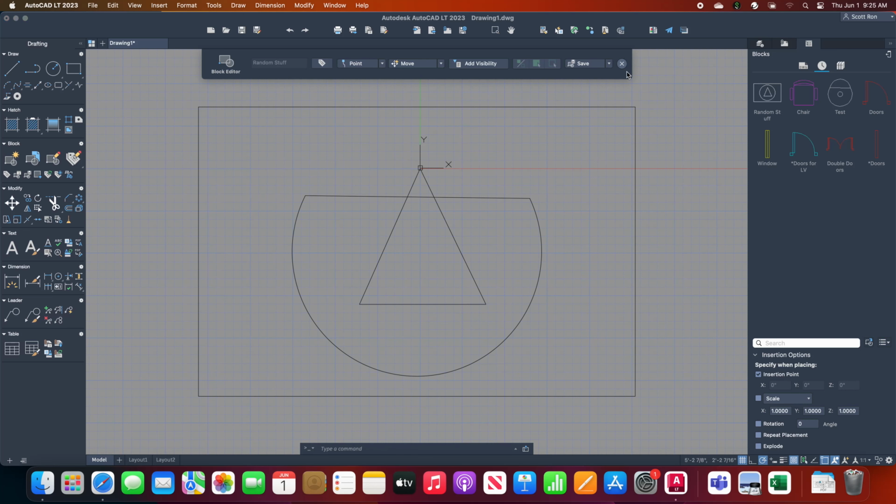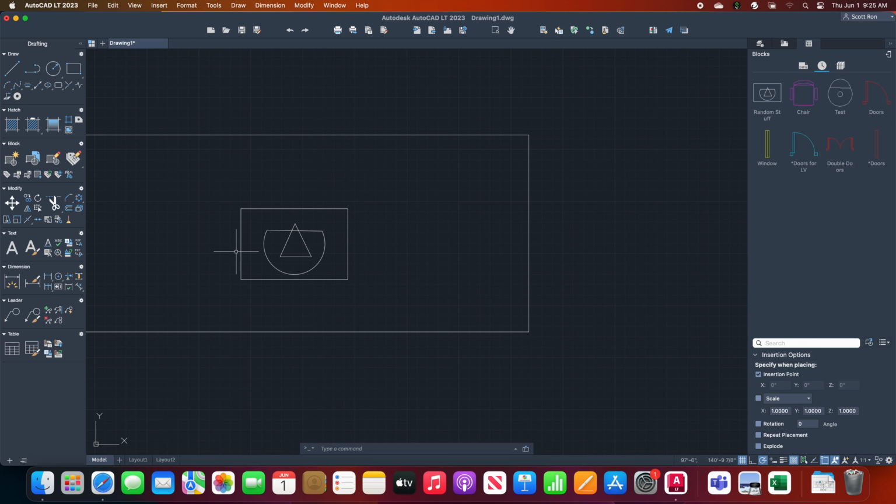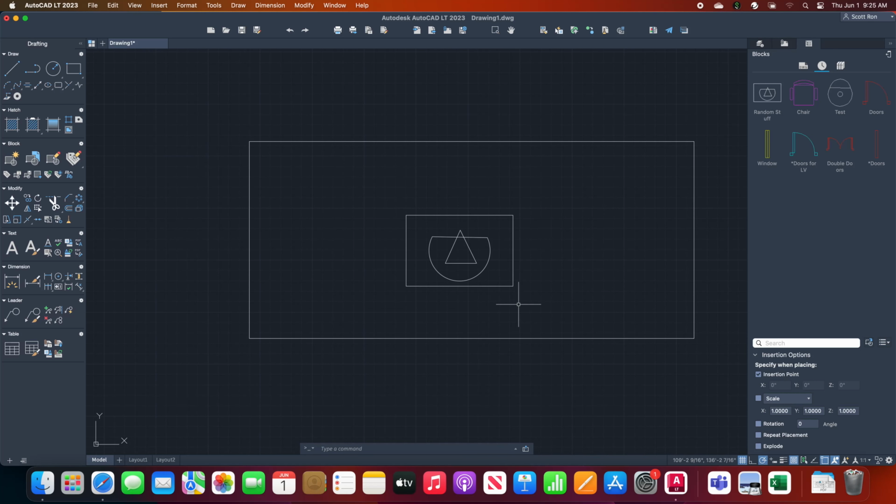It's technically going to save. So once you close, you see, now if you see the block going forward, we'll have those changes. So in case you want to change something and have it reflected going forward in all your blocks, you can do that. Simple. So if you want to edit your block, that's the way. Go to this third option in the blocks, which is block editor, and then you can change everything in there. Okay? Cool.